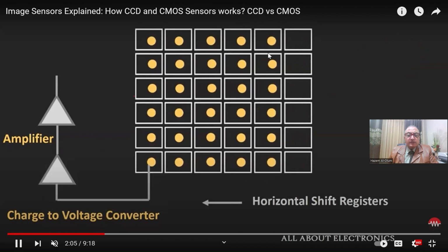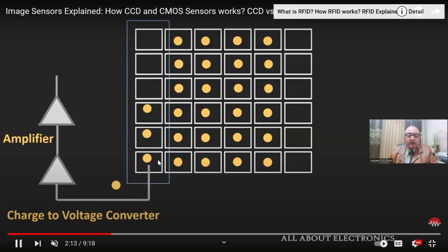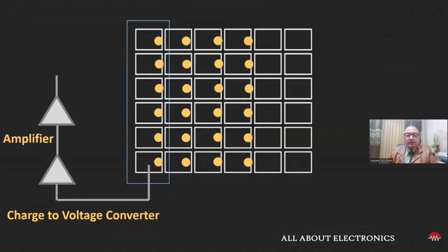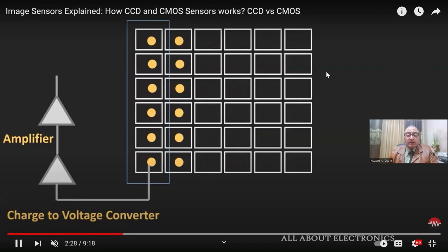So this is the shifting process that can be done. We just shifted by 1 pixel. Then the readout is done serially, as you see here, one by one, and this will give us how the operation is done. And the process is repeated step by step until we finish dealing with all these potential wells during the shutter time, waiting for the next exposure to light again.